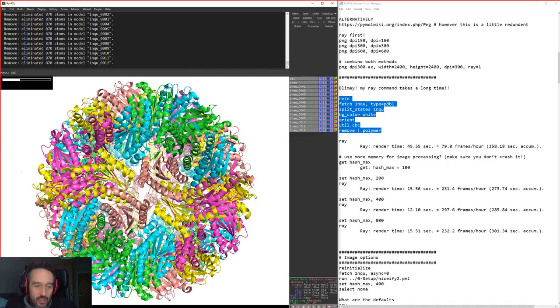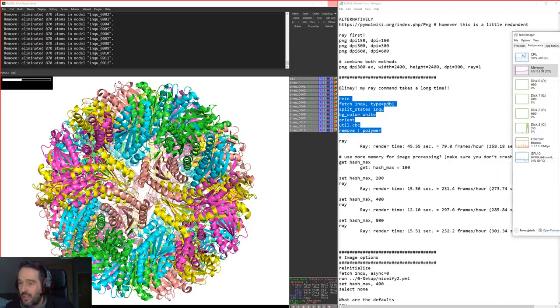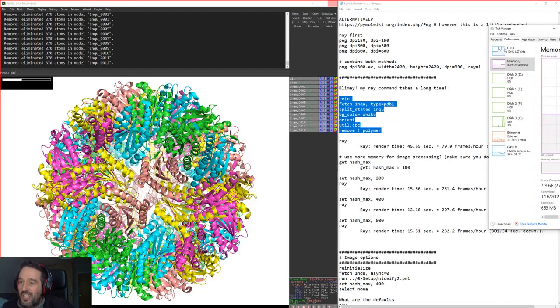So when you've got something large and complicated, something that has an interior, of course, you're hitting the ray from various different light points, and what we can see while we're going here is that our CPU is getting maxed out, but we're using a correspondingly small amount of our memory while we're processing our images, and that is not very efficient, because actually we can ask Pymol to allocate more memory into our processing, and therefore relieve some time on our CPU.